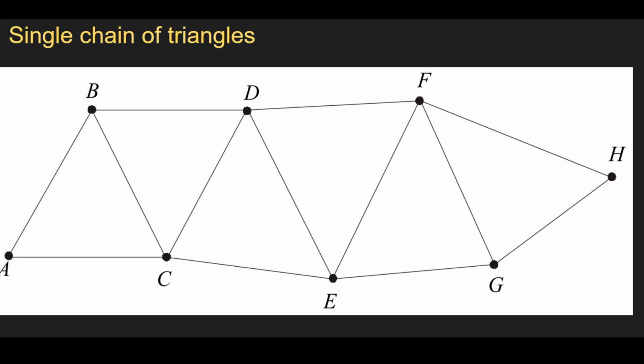You can see. So if you have a check base AB, and we can calculate for HG. And the disadvantage for this is that we only have one route for computing HG or GH. So what do you mean when you say one route? So if we know AB, then using sine law, you can calculate BC, right?